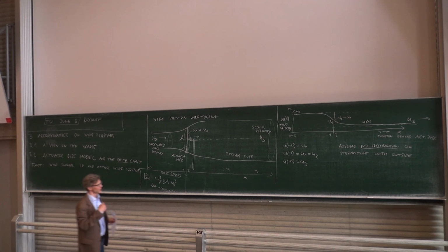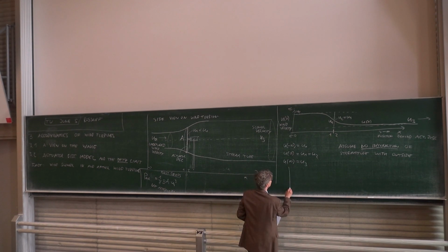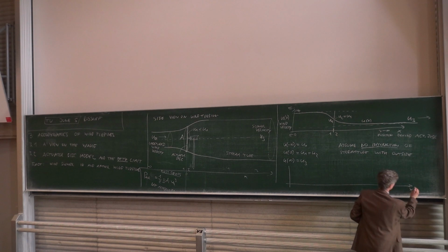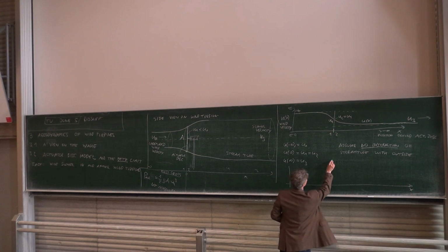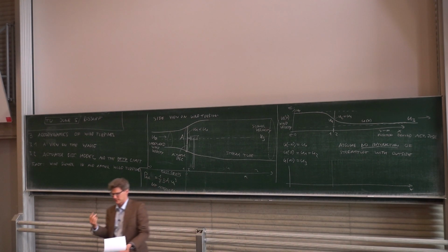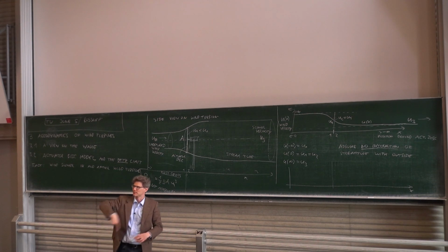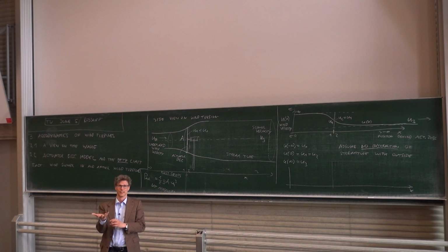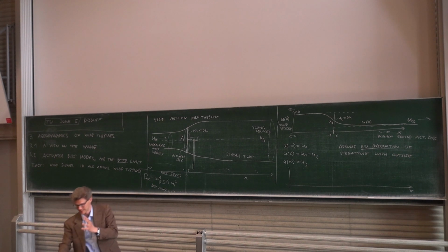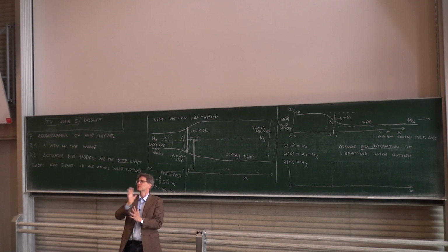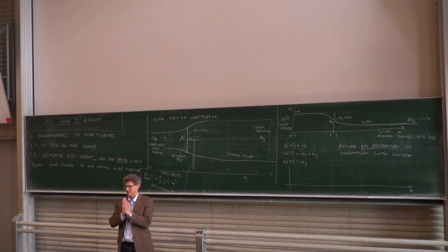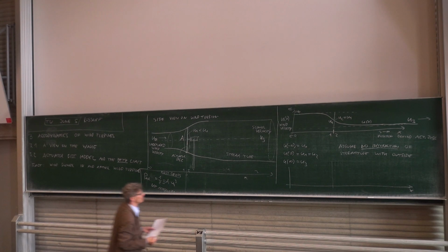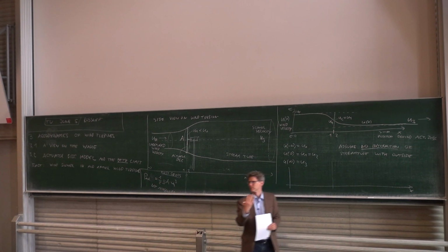So when we look at the pressure along the same axis, with the position behind the wind turbine, and here's my wind turbine somewhere, what is an actuation disk in essence? We know that it's rotating blades that have a very strong force on this air while it flows through them. But you could also think of it like when you cook pasta and put it into a sieve. Such a sieve in the air will slow down the air, and it can only do so by pushing against the air. And what does it mean if something pushes against the air? There must be pressure. So there must be a pressure difference at this actuator disk, and there must be a higher pressure before than after, because we slow down the air.